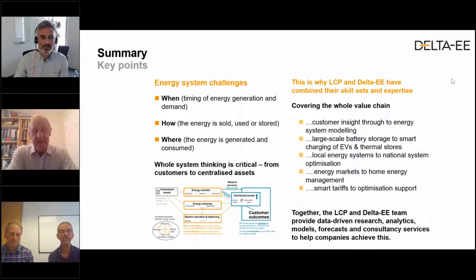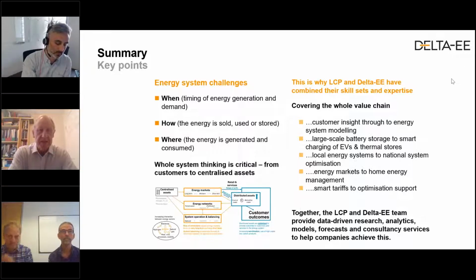Certainly we were very keen at the beginning of the smart meter program, in its inception stages, to make sure it had the functionality not only to enable energy retail markets to operate more efficiently, but also to provide valuable information for distribution system operators. They can then monitor load growth at an individual feeder level or substation level, right down onto the LV network, where currently the monitoring level is quite sparse. It does it in an agnostic way, so you don't pick out individual customers, but you can aggregate through the MPANs to individual feeders and substations. It's a great way of tracking what effect EV charging or conversion to electric heating is having on your local LV system. So you can begin to see constraints emerging and have time to do something about it before it becomes a major issue.